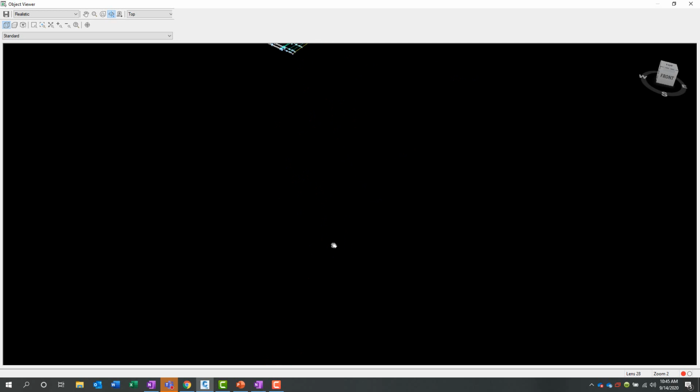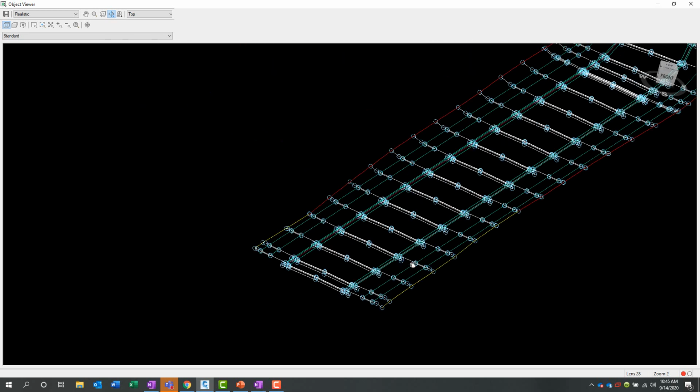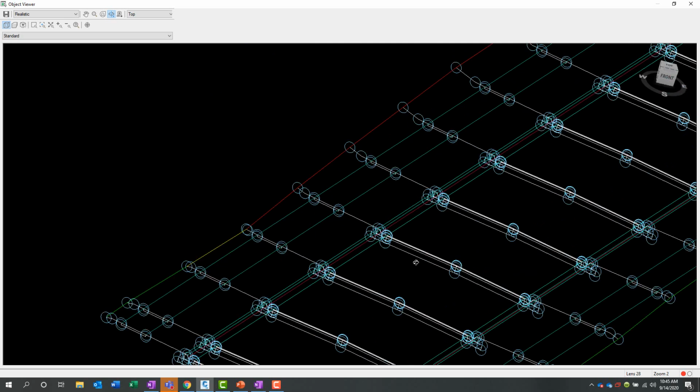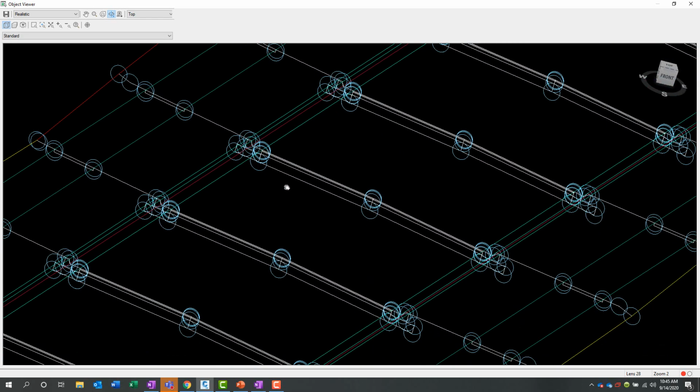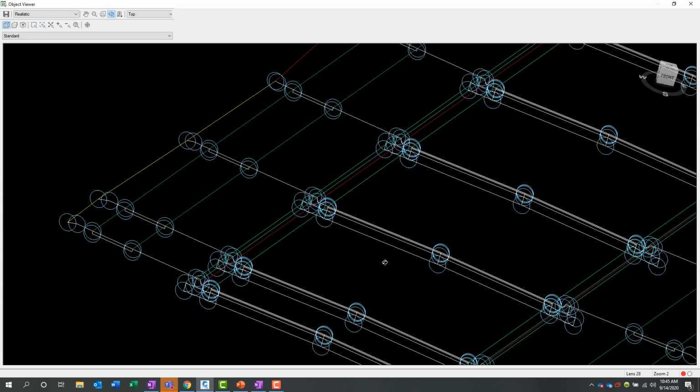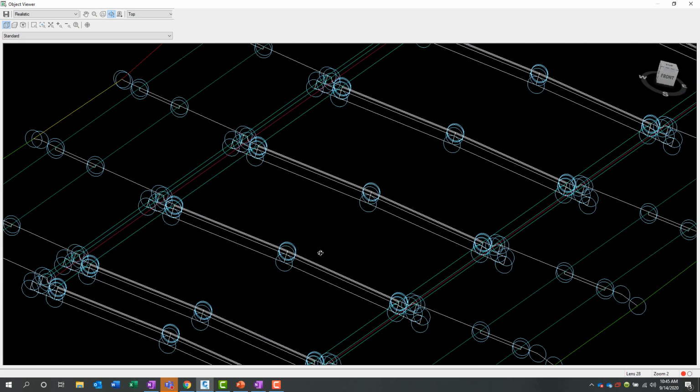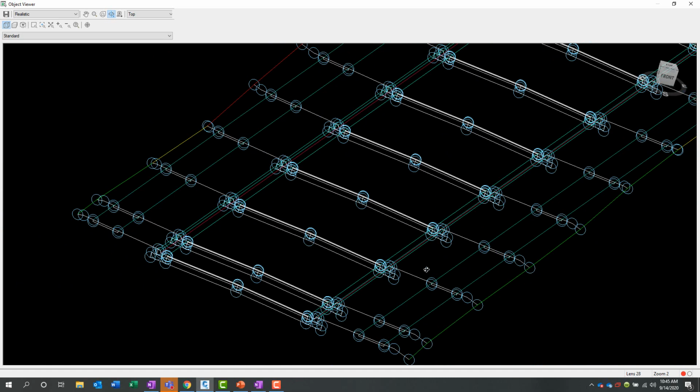So we get a full, what looks like our subassembly at every insertion point. And I did use the larger circle marker for the points. Hopefully that's making sense, how this corridor is built and how the codes actually influence the visual appearance of that corridor.